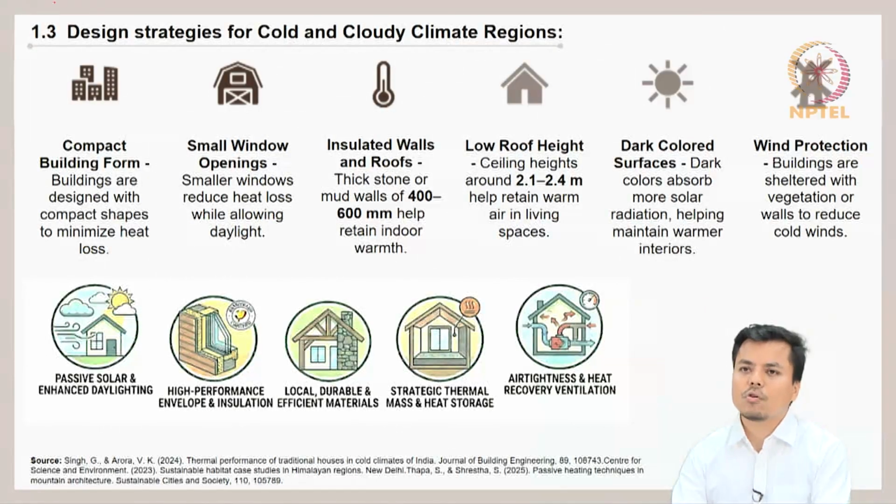Let us first focus on design strategies for cold and cloudy climatic regions. In cold and cloudy, the design should be in a compact built form. Buildings are designed with compact shapes, so it minimizes heat loss. The more compact a building you design, the heat loss will also be minimal. Then small window openings. The opening should not be huge in size that it allows heat to escape. Smaller windows reduce heat loss while allowing daylight to enter.